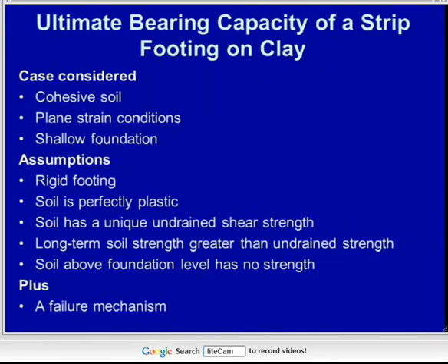When we dig excavations, it's the other way round. We dig an excavation, we unload the soil horizontally, and there the undrained strength is greater than the drained strength. It makes excavations particularly hazardous. It's why nobody ever enters an undrained excavation. If you dig a trench to put, for example, sewer pipes in the ground, very often that trench will stand vertically open and look perfectly safe.